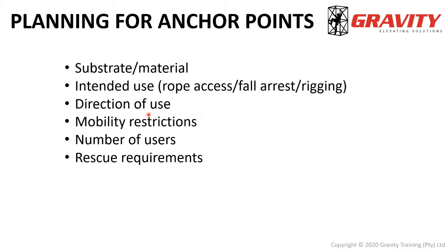Then mobility restrictions, I'll get to that in a second as well, in more detail, but that refers to placing an anchor in such a place that prevents the user from actually reaching the areas where they need to work. Okay. Then, of course, always consider the number of users on a given system so that you ensure you install enough anchor points of sufficient strength to compensate for that number of users on that system or lifeline or anchor point, whatever it may be. Okay. And that is especially important when it comes to rescue requirements.